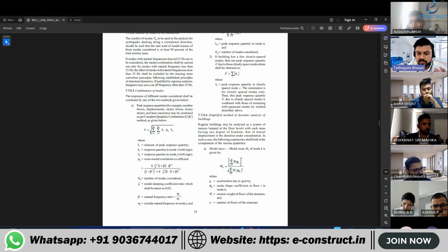Response spectrum case is there, no, Spec X and Spec Y. Over there is a modal combination type where we keep it as SRSS. So this needs to be made as CQC. Okay, so this is the thing that CQC is being done.